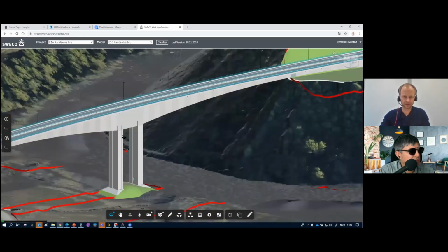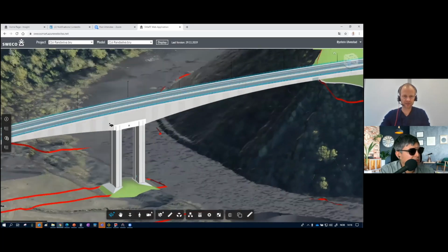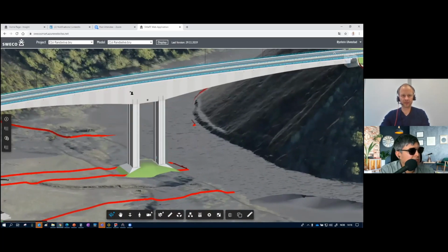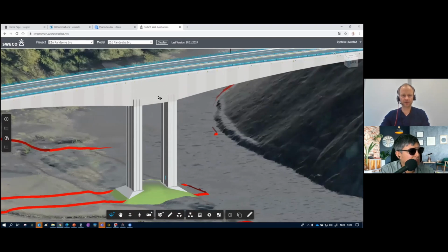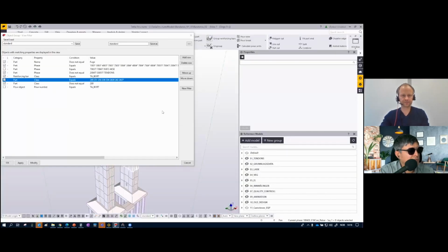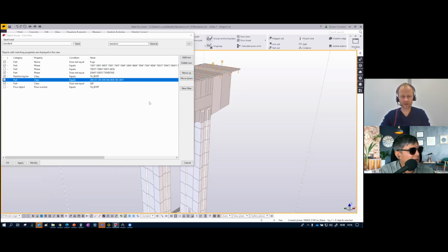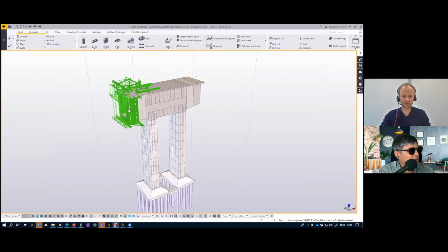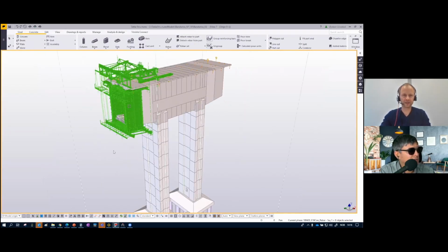When they start building this part, they do the hammerhead first, and then they build the first segments on either side. And to build these segments, they need formwork. Correct. So you'll have one of these on either side of the structure.